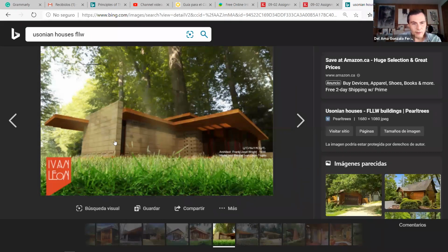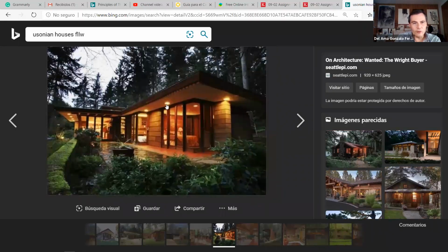So that works well. Especially if you are designing small buildings, having the north facade like this, very massive with small windows, and having the south facade like this with huge windows and long overhangs, that's a key to success. So if at the end of this course you learn that the south elevation is different from the north elevation: if we are working in New Hampshire, or in a cold country, this is the key. If we are working in Florida, probably this is not the right option.